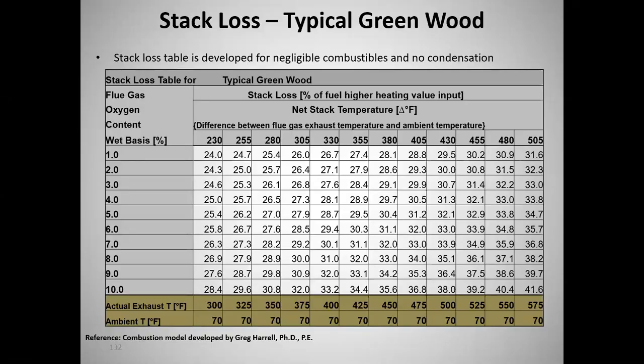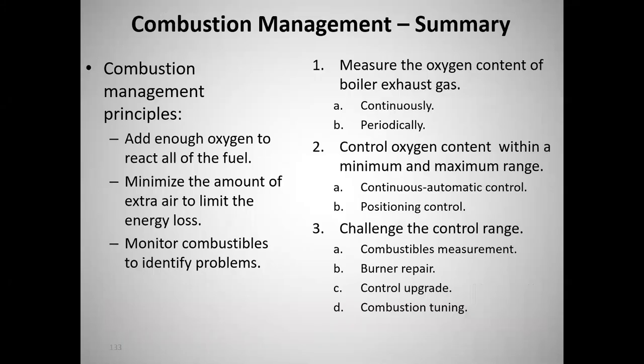Okay, so that's the green wood. Now, our summary slide on combustion management. Basically, our management principles are pretty simple. Add enough oxygen, i.e. air, excess air, to react all the fuel, but at the same time minimize the extra air to limit the energy loss. And we want to measure and monitor combustibles and excess air levels to identify problems.